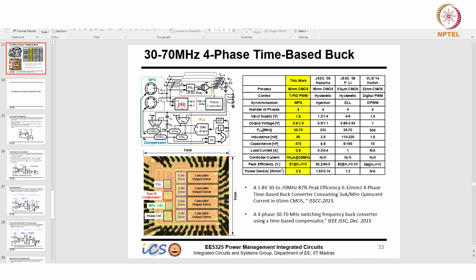And then you can think of the multi-phase generator as nothing but dividing this clock by 4 and separating out all 4 phases. So a single phase goes here at 4x and is then separated out into 4 phases, rather than tapping the 4 phases directly from the VCO, because that may have mismatch. So here you get a very good phase match.